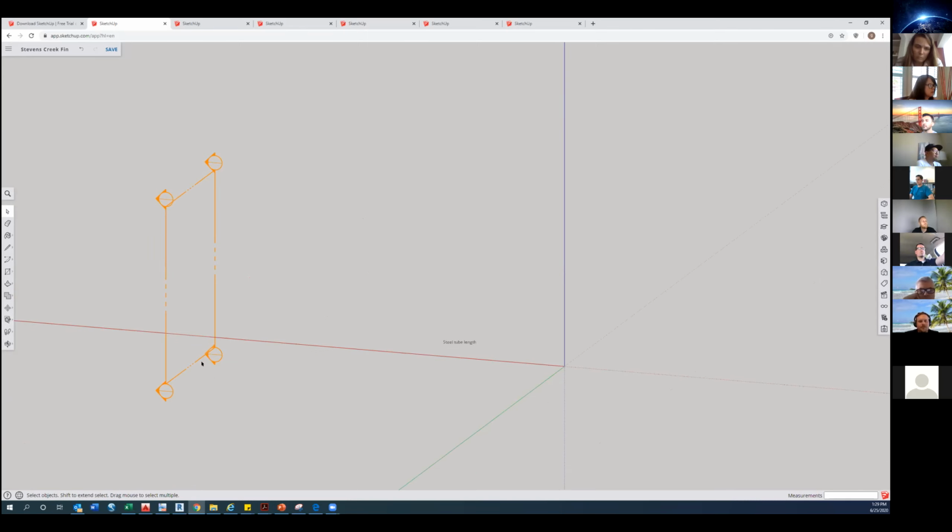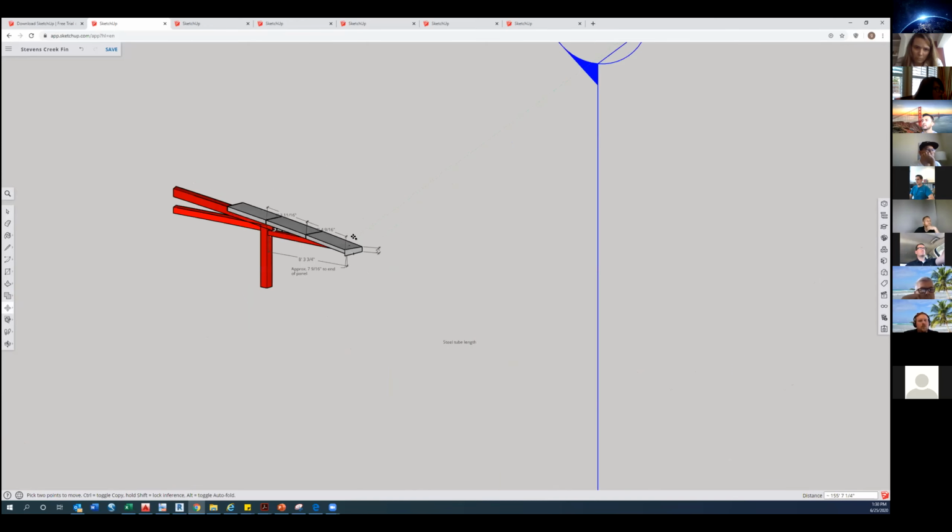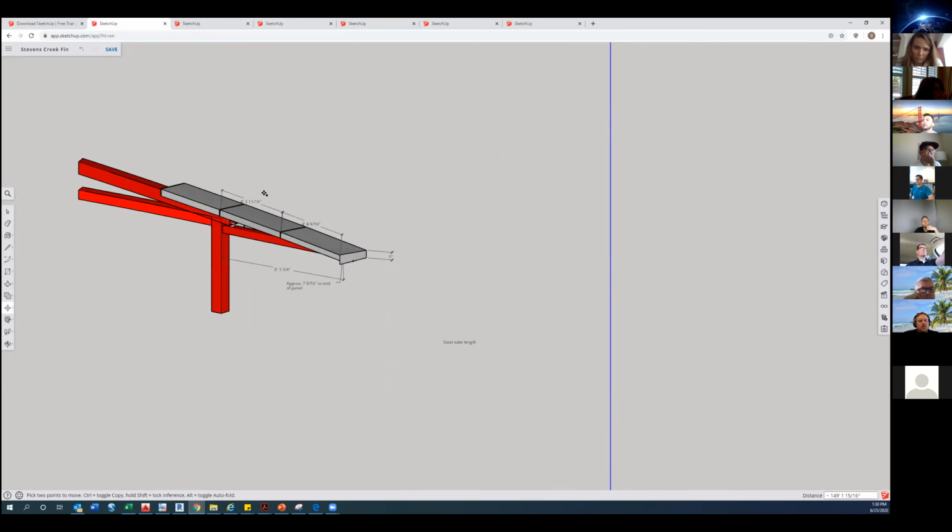In this case, the section was placed way over here, so that's why everything's invisible. But if you press the move tool, and then you drag it along the red axis, it's going to uncover it. And then you can zoom in, while still holding the same command. And once you go through it, it'll start cutting it.